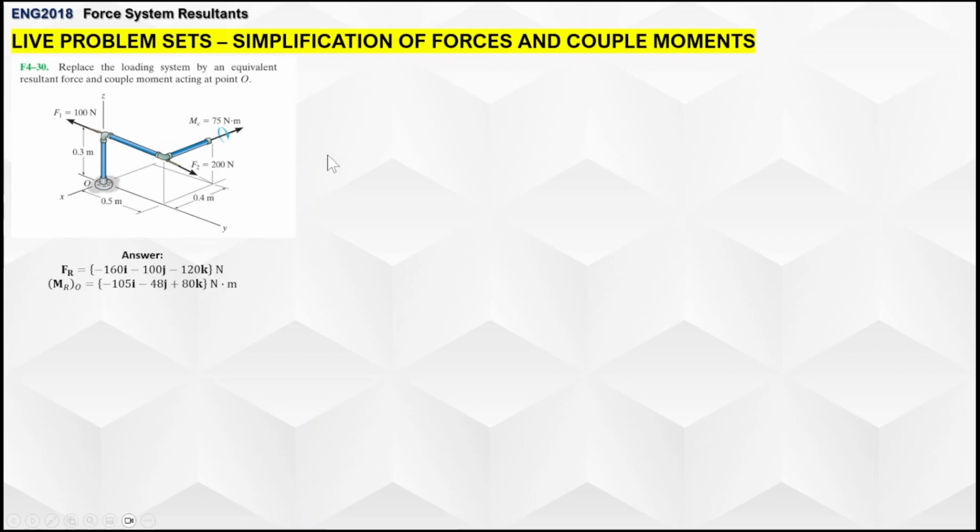And when you're dealing with forces in 3 dimensions, all you have to do is apply the same rules in simplifying forces and couple moments in 2D, but you have to convert them into Cartesian vector notation. Okay, so just like what I said during my pre-recorded lecture. So we're here to find the resultant force and also the resultant moment in Cartesian vector that is acting at point O. So again, theta is not needed, since the problem is in 3D and the final answer is in Cartesian vector notation.